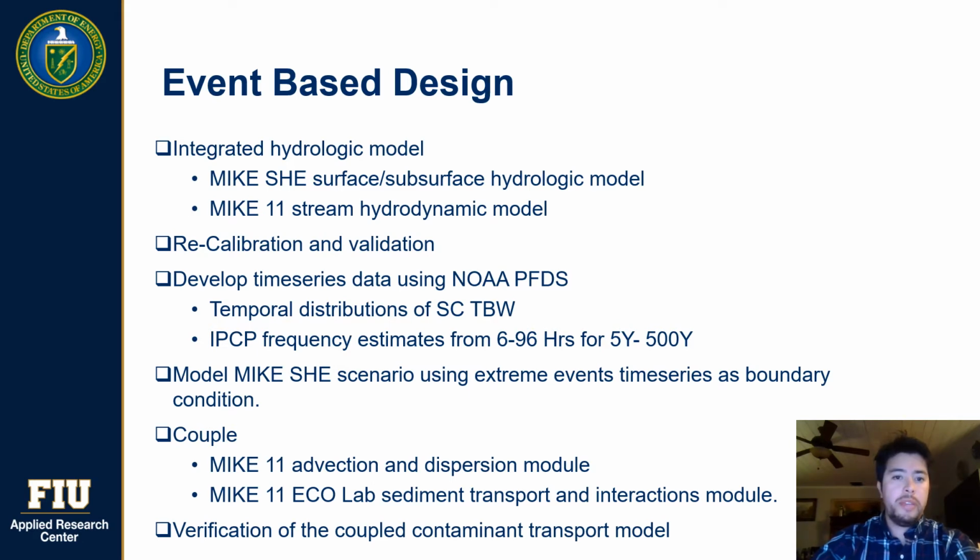Regarding the event-based design, we prepared the model domain for the analysis. So we integrated both models, MIKE SHE and MIKE 11, and we had to recalibrate it to different groundwater levels, and flows were centered at the outlet of the watershed. Parameters were optimized and selected through literature review and hydrology modeling standards.